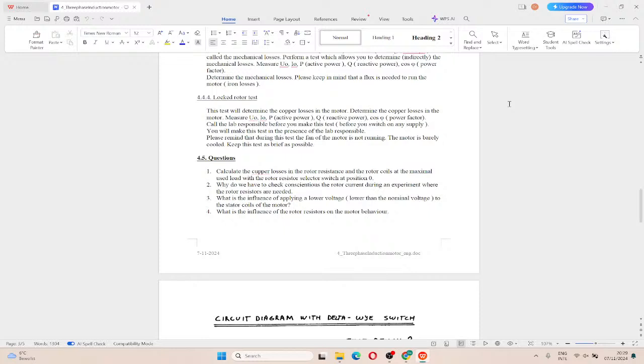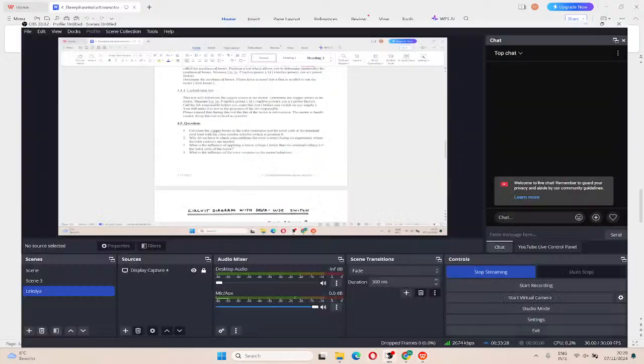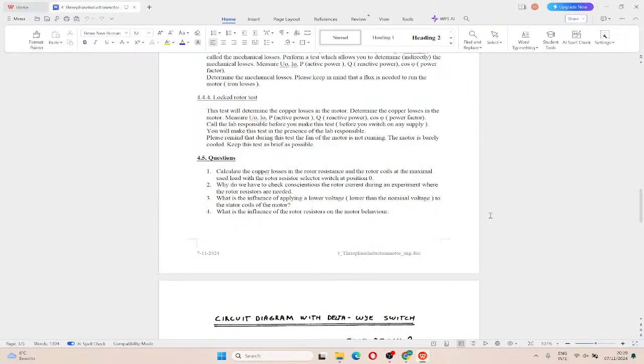Okay. So we need to lock it, make it not turning. It's basically about the dual loss of the rotor. So it should not have output. No. The lock rotor test is you look at it mechanically. Mechanically? Yes, mechanically. So still no need. Yes, we need to short circuit it. Yes, we always need to short circuit.